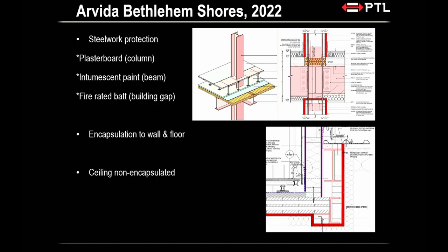All right, and the other thing is this building design is complex because a lot of time you have the apartment at 30 minutes, and then you have all this communal area, right? The communal area then has a 60-minute fire resistance rating, right? So this is what it is showing you here. So some part of this floor is actually 60-minute, we run encapsulation, and again, we come across quite a bit of steel detail. There's a PFC supporting the floor, and then there's an I-beam supporting the roof because, you know, the different levels and stuff.